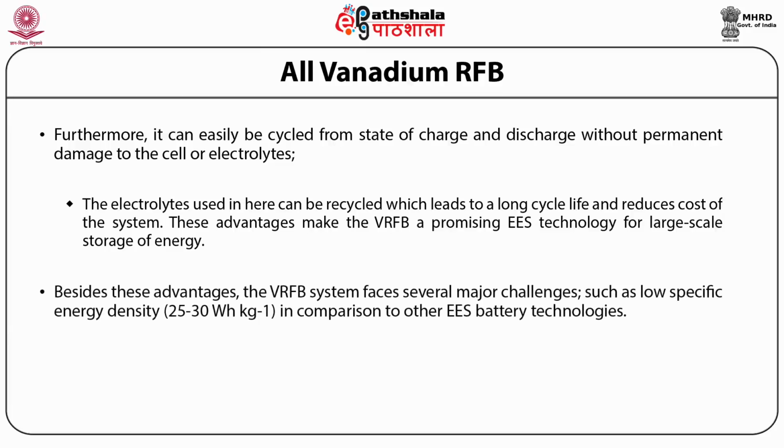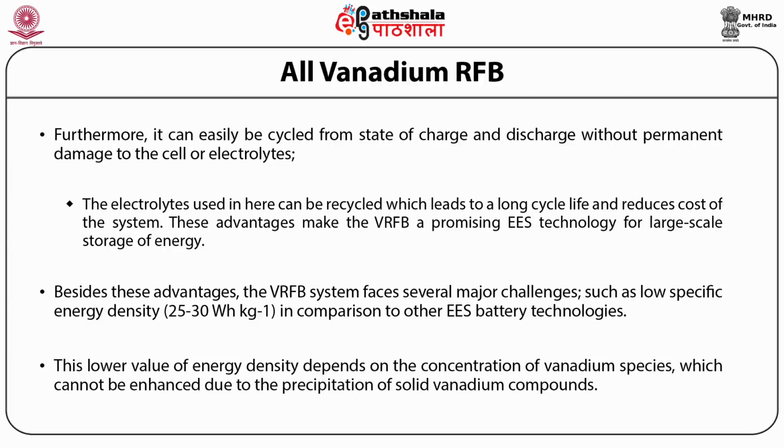Besides these advantages, the VRFB system faces several major challenges, such as low specific energy density in comparison to other EES battery technologies. This lower energy density depends on the concentration of vanadium species, which cannot be enhanced due to the precipitation of solid vanadium compounds.